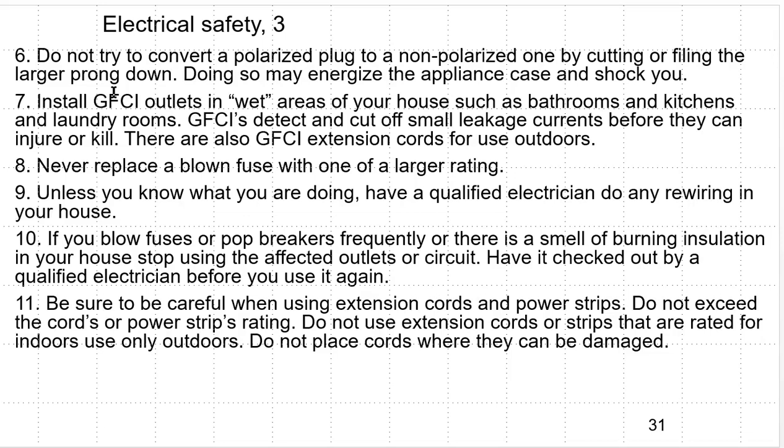Be sure to be careful when you're using extension cords and power strips. Do not exceed the cord's or strip's rating. Don't use extension cords or strips that are for indoor use outside; use only those rated for outside. Don't place cords or strips where they can be damaged.